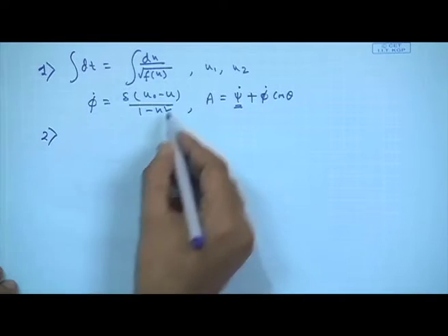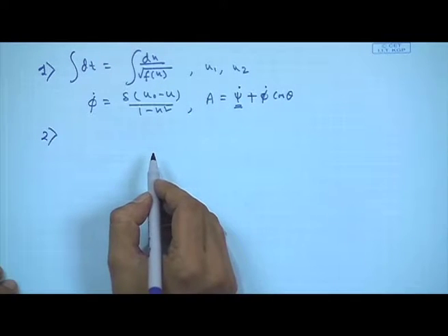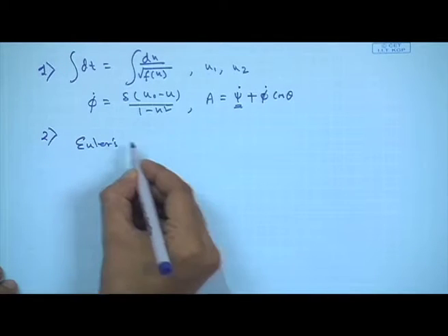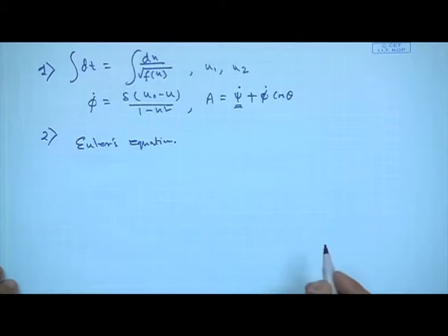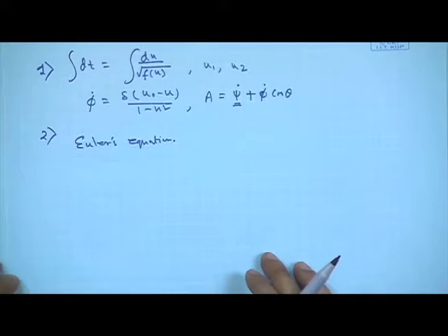The second way is you do not go into all this, you start from the original Euler's equations. You have three sets of Euler's equations, you set some initial condition, and the three first order differential equations can be reduced to second order differential equations with the help of Euler angles. These three equations can be simultaneously solved by a second order Runge-Kutta algorithm. That is a doable thing, and I would say it is numerically less challenging compared to solving the elliptical integral, because the elliptical integral has many typical properties which might give you a very problematic approach. So these are numerical solutions.